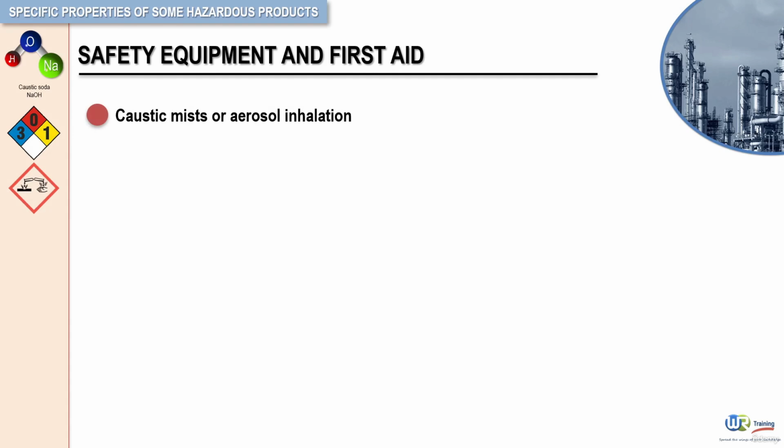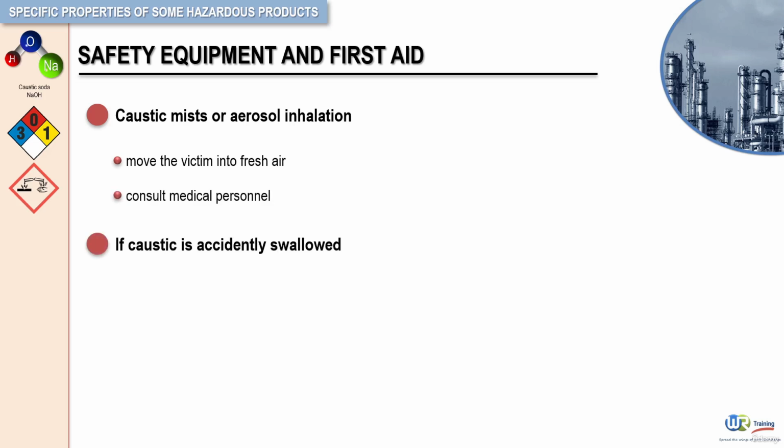In the case of caustic mists or aerosol inhalation, quickly move the victim into fresh air and consult medical personnel. If caustic is accidentally swallowed, drink large quantities of water and contact the physician, and do not induce vomiting.